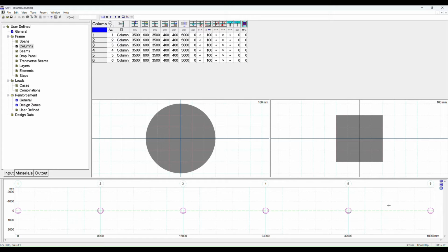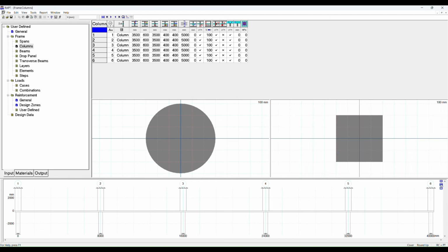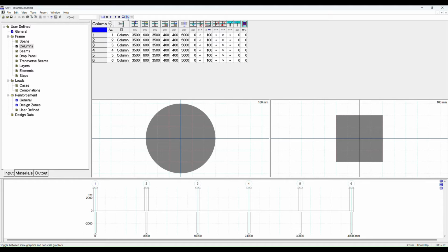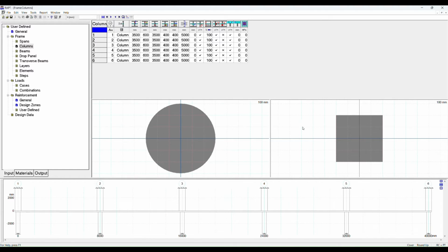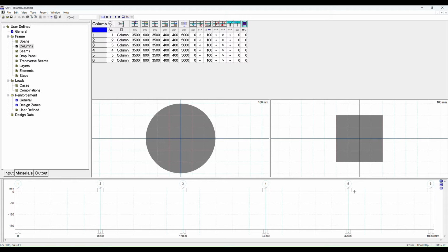At the face of the column, bending moments will be taken into the column. But there will be also a portion of bending moment in the slab that's taken into the side of the column. And the equivalent column method is a way to calculate that total moment that goes into the columns. Next up is just that elevation, which I said I'd show you, which that's now to scale. That's to scale. That's not to scale, but you see the full elevation, and then that's a sort of a close-up of the slab so that you can see your reinforcement.